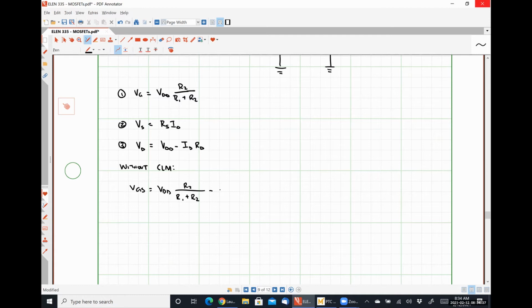The first thing that we are going to do, or we're going to make a large assumption, all right? We are going to assume that anytime we have this full resistor biasing circuit, the transistor is operating in the saturation region. We're going to have to come back and verify that. The reason that we always assume that it's operating in saturation region, you will shortly see, is because the math is easier, all right? If we assumed a triode operation, we would have 2 quadratic equations that are coupled to each other that we would have to solve for, which takes forever to do iteratively. It's really quick to do in MathCAD, as you'll see. So it's definitely a use your computer kind of situation.